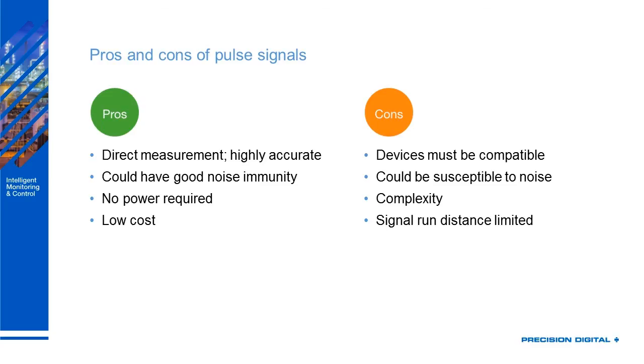They could potentially have good noise immunity. Because you just have an on-off state, if I have a nice strong pulse, let's say in the 10 volt pulse range, because I have a pulse generator that's externally powered, and my low is at 0 and my on pulse is at 10 volts, well, that's a nice strong signal, and noise is going to have a hard time impacting that.